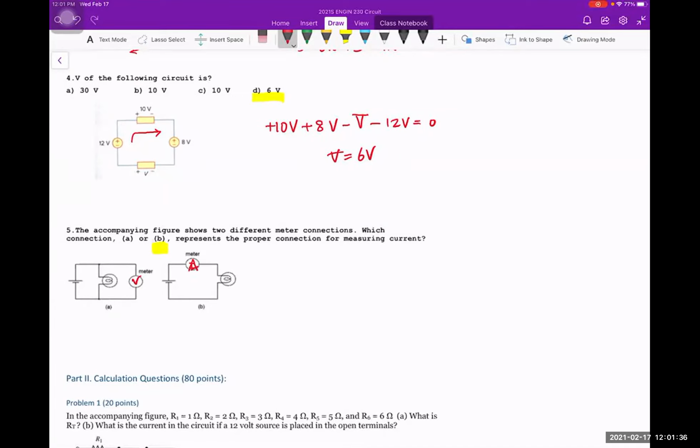Now, if you wanted to measure both things at the same time, then you should put a voltmeter in parallel with the device as well, right? Okay, now in the lab, we told you different combinations. So you could have two different scenarios. Let's say this is a light bulb here, and you can also put an A in here and put a V in here, and which one give you a better result? When I say better result is more accurate result, right?